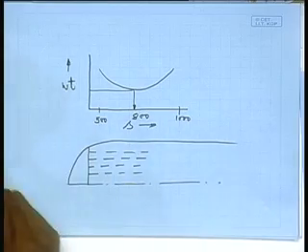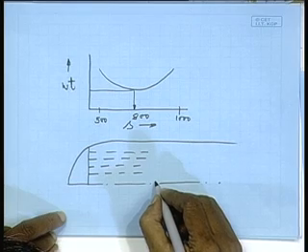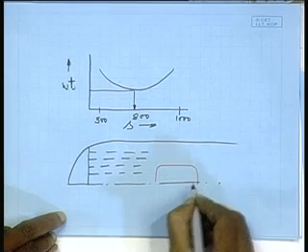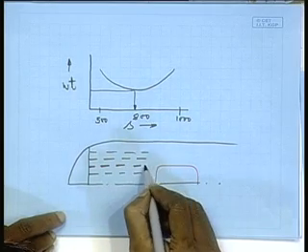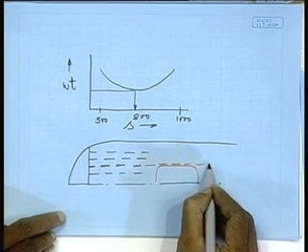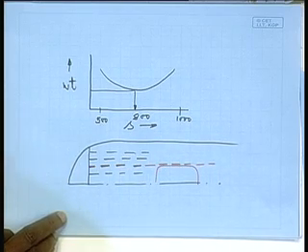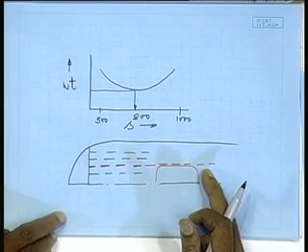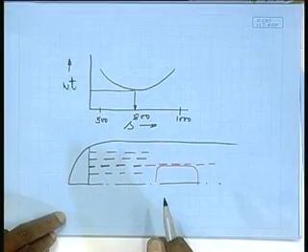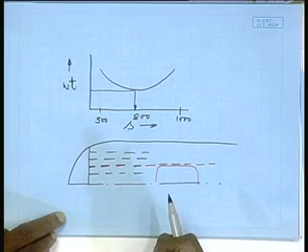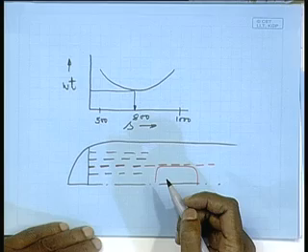And if you are providing a girder here, suppose I have the hatch opening here, then this particular longitudinal is replaced by a hatch side girder. I will not make the hatch opening arbitrarily, I will make it in such a fashion that the hatch side girder also comes at some multiple of frame position. Why? Because then it becomes easy to keep track of where the stiffeners are.